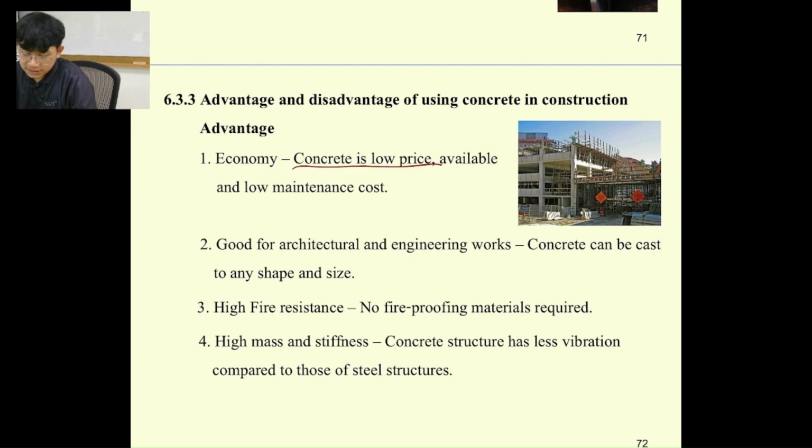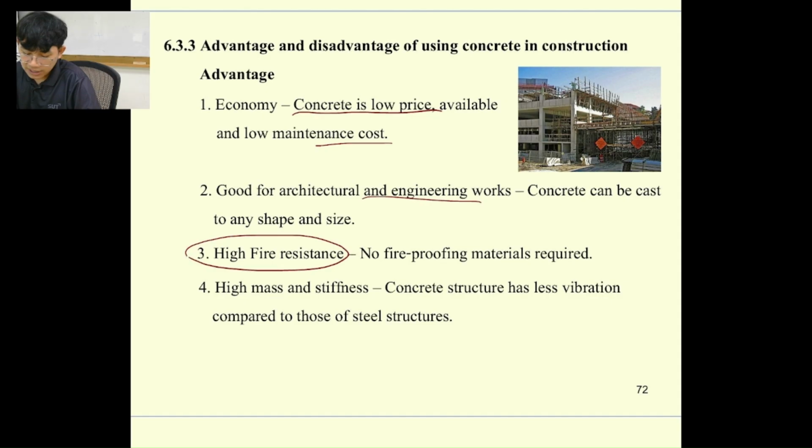So the price is really attractive, and maintenance cost is low compared to steel. It is also good for architectural and engineering work, which means we can cast it into any shape. If you would like to make it square, we can just do it. If you would like to make it really complicated, we can bend the formwork to get that shape. It also has really high fire resistance, so no fireproofing is needed, and we have really high mass and stiffness.